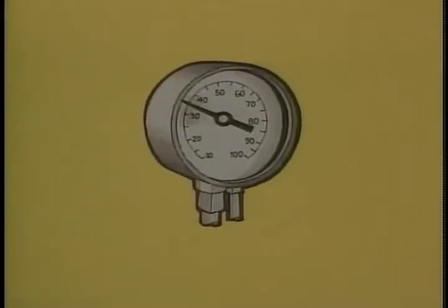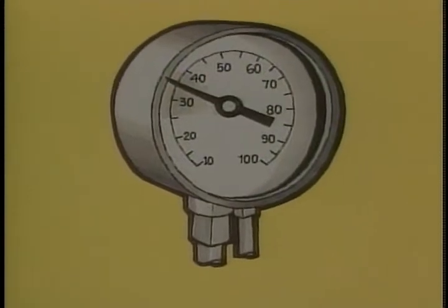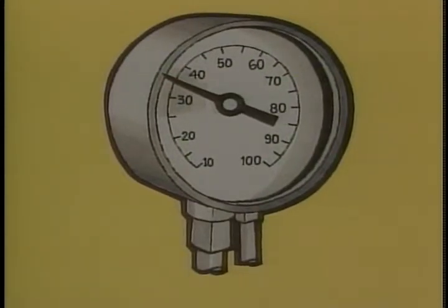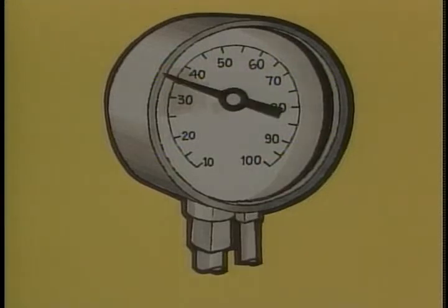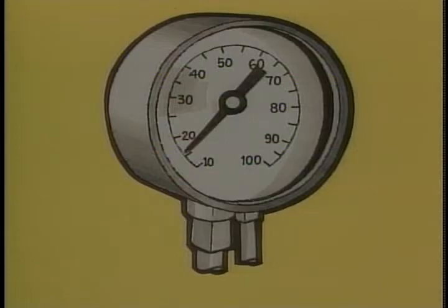Another common problem that'll result in a plugged line is low operating pressure. The operating pressure is important because most of our systems operate on fairly low pressures, in the 30 to 40 psi range. If the pressure drops much below that, the system will tend to clog. It's real important that you not operate the system above these rated pressures, but it's just as important to make sure you've got enough pressure.